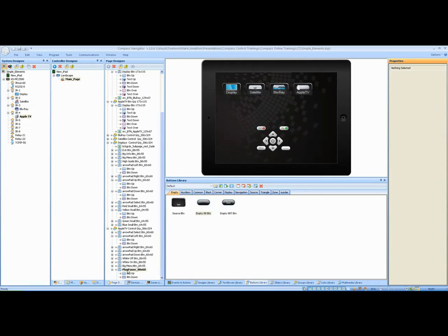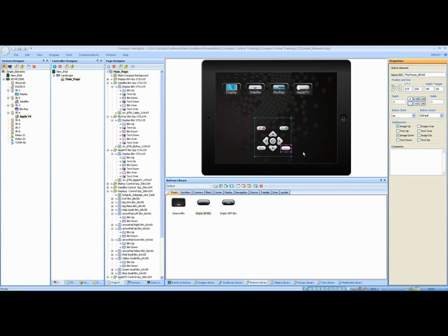And we could even, just for testing purposes, go ahead and press Control E to emulate and just ensure that as I press this button, it does in fact go to the black position, very similar to how this prepackaged menu button does. There we go. So let's now exit our emulator mode by clicking in the tree and pressing Control E.